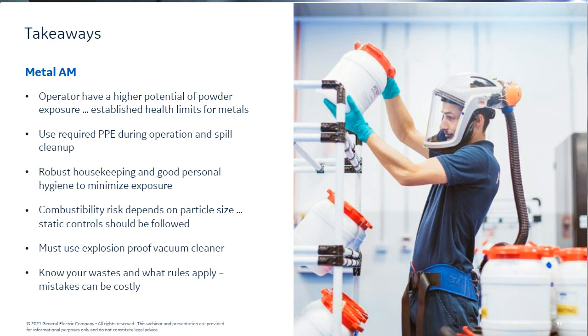It's more key than on every type of shop floor, but in this case, it's really key. And also good hygiene practices for your employees themselves, so that they don't take the powder out of your production environment and take it home to their children or wherever. The combustibility of the materials and also the flammability risks depend mainly on the particle size. Also here, you need to understand that.